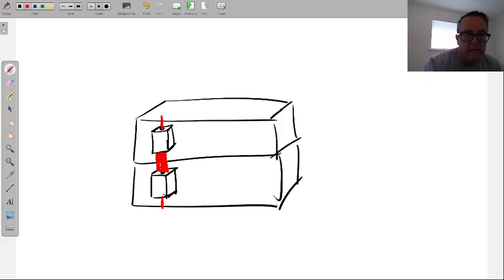This little pin will go through both breakers. And now, physically, if you shut one off, that pin takes the other one with it. The other thing that can happen is this breaker trips for whatever reason, say whatever was on this circuit had a short circuit or a ground fault. They both shut off at the same time, and we don't get that scary neutral effect.